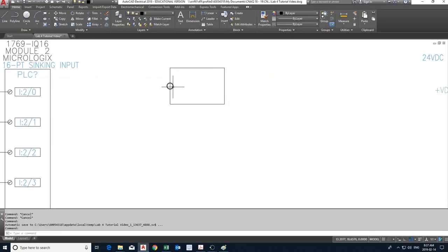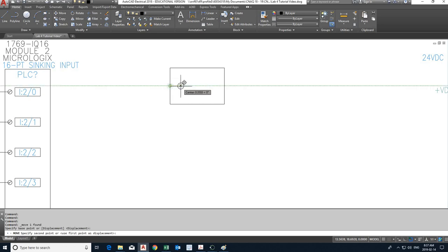So now I'm going to take this, and then we'll say move. It doesn't matter from where, but I'll choose the center. And then at 0.6, comma 0. Enter. That's the first one placed. At 0.6, comma 0. I'm only going horizontally in the positive direction.